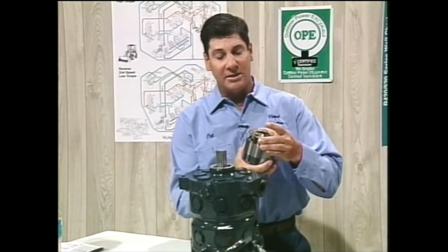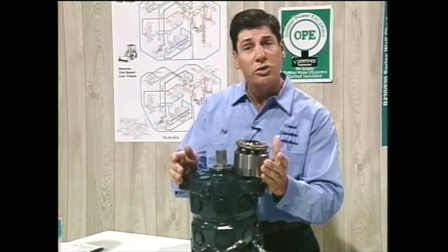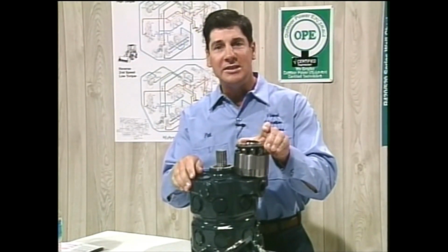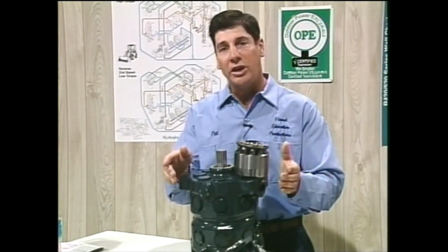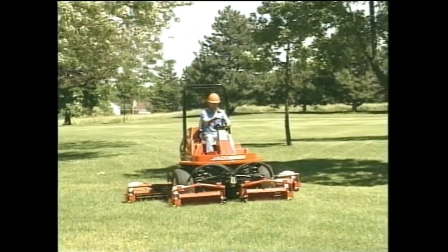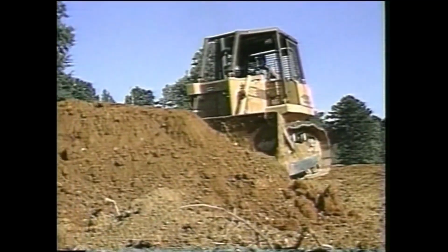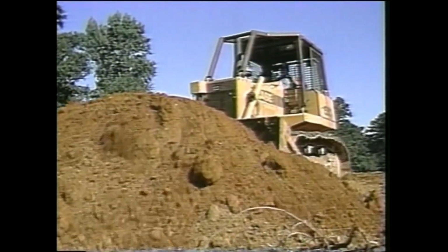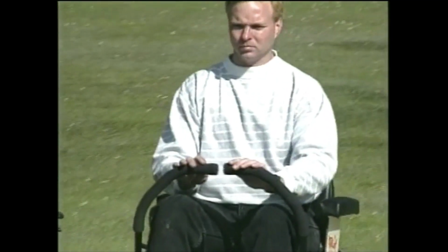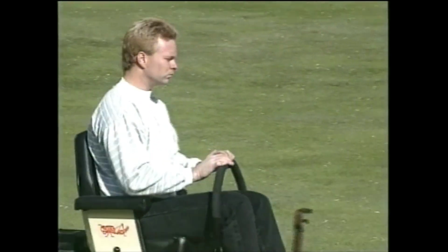Variable displacement piston pumps are adaptable to many applications and are commonly used when the volume of oil pumped needs to be varied without changing the speed of either the pump or the engine. For example, in hydrostatic transmission systems, the engine and variable displacement piston pump run at a constant RPM. Ground speed is controlled by varying the oil output from the piston pump to the piston motor.